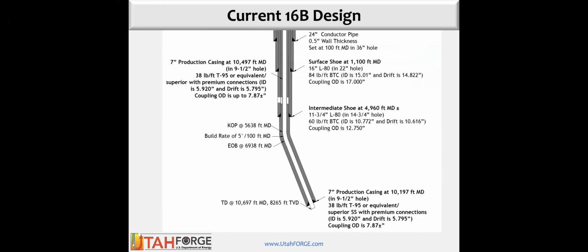So right now, essentially the casing will run from the bottom of the measured length at 10,006. The casing would end at about 10,200 feet measured depth. The total well will be about 10,700 feet. So there, as I said, 500 feet of open hole.